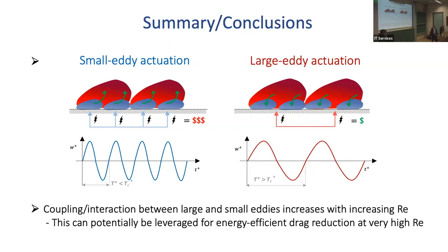What is the value of the amplitude of the spanwise wall oscillation with respect to the typical wavelength in the spanwise direction? Yeah, so we had to make an estimate. I made an estimate based on the wavelength being about one boundary layer thickness. How important that is, I don't know, but more important, a spanwise velocity around 12 seems to be the magic number. That's about the convective speed of the big structures in the skin friction as they move along the wall. So you need to target things around that convective velocity at the wall, and it makes sense.